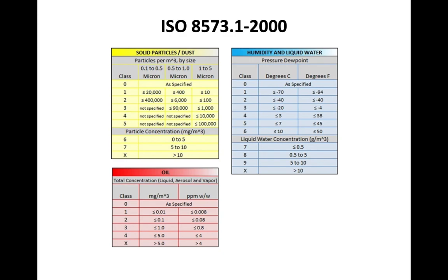They require class 8. And for class 8, the pressure dew point should be in between 0.5 to 5 degrees Celsius. It will be provided by refrigerant dryers.